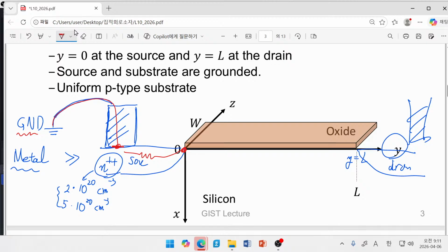Is it really 0 nanovolt, 0 picovolt, 0 microvolt? I cannot say so. However, since the voltage difference across this system can be written as VDD, because we apply 0 to the source contact and VDD to the drain contact, which is on the order of 1 volt, 0 point something, a small increase at this point can be safely regarded as quite close to 0.